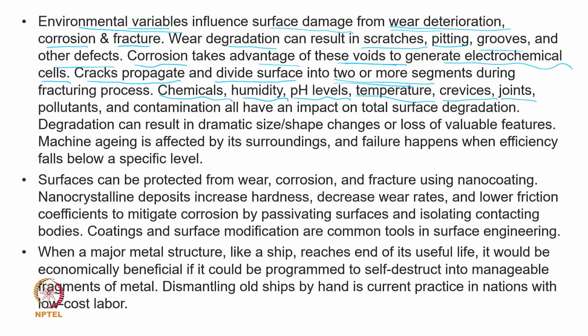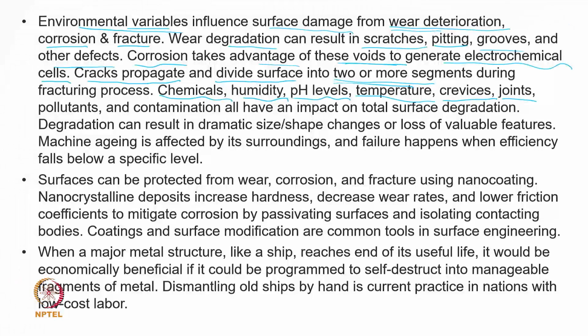If there are crevices or joints, as I mentioned in the case of the bridge, naturally there is a problem, because most of the time we follow the fabrication process, we really do not measure each and everything properly, and there will be some sort of crevices, some sort of gaps sufficient for corrosion to take place, or for the electrochemical cell to form there. Now, how severely that can act depends on the different environments, but joints are also a major issue. So, if I can really develop a product without any joint, that will be the best.